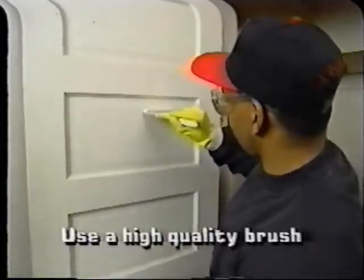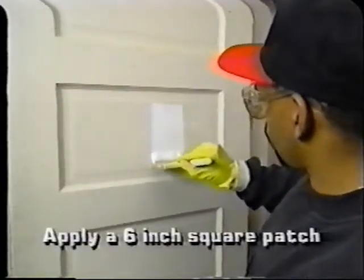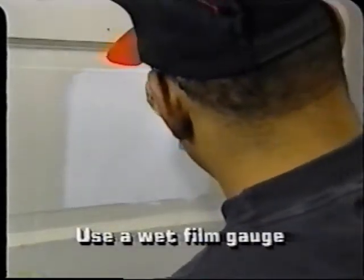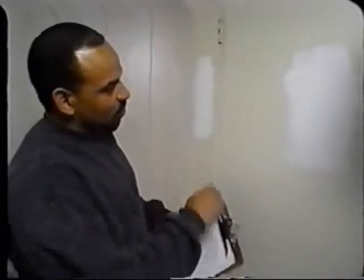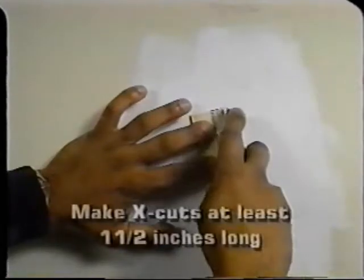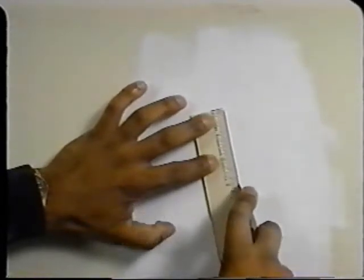Begin the patch test by applying the encapsulant to a 36 square inch area. Usually this will be a 6 by 6 inch square. After the encapsulant is applied, use a gauge to confirm that it meets the manufacturer's recommended thickness. Allow the encapsulant to fully dry and cure. Once the encapsulant is dry, visually inspect it to make sure that there are no signs of blistering or cracking. Next, using a sharp utility knife and a straight edge, make a 1.5 inch X cut into the patch down to the substrate.